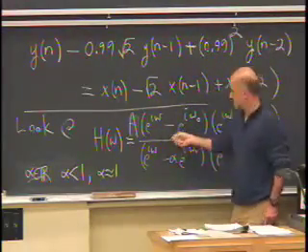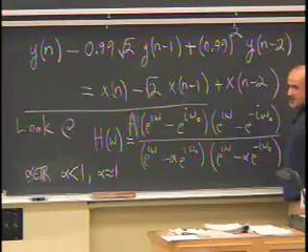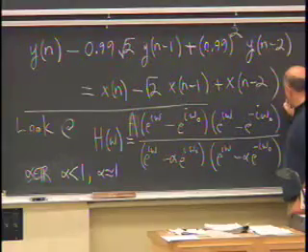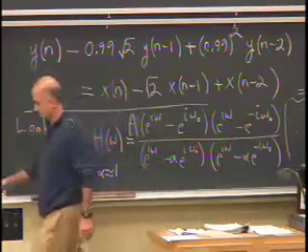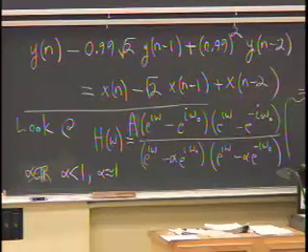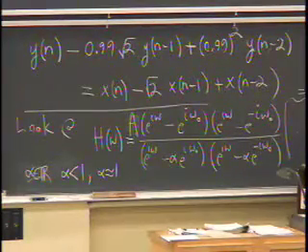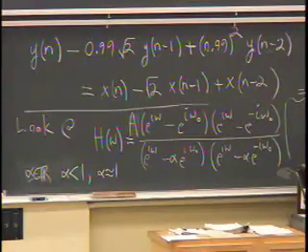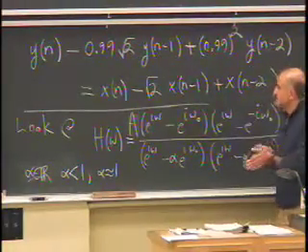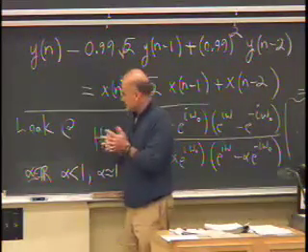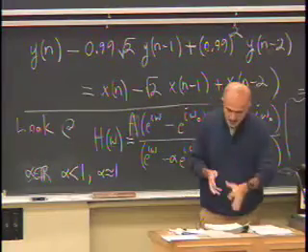If I allow higher order terms, I can have factors multiplying this out whose magnitude is exactly 1. There are filters called all-pass filters. All-pass filters are somewhat interesting. When you look at the magnitude response of an all-pass filter, it's constant for all frequencies. The only thing they do is fiddle around with the phase of the input signal. So this is general modulo an all-pass filter sitting in front. But aside from that, yeah, it's the lowest order, most general form of a notch filter. Let's take a break. And then I'll move into analog filters.